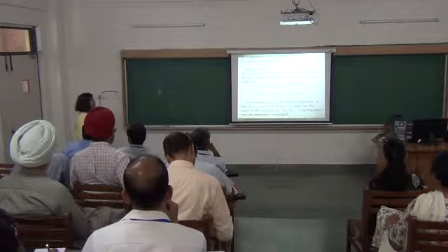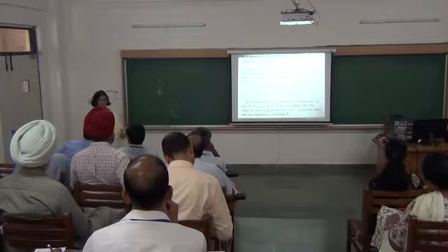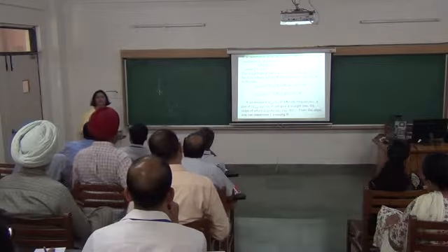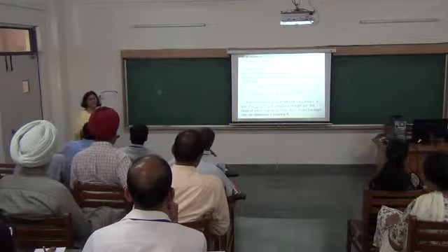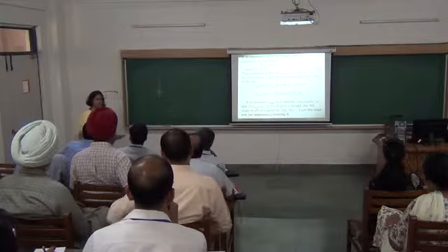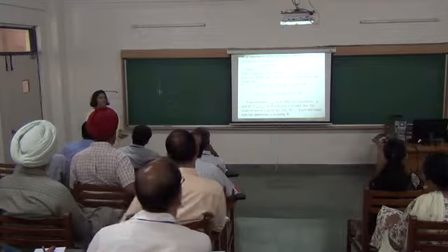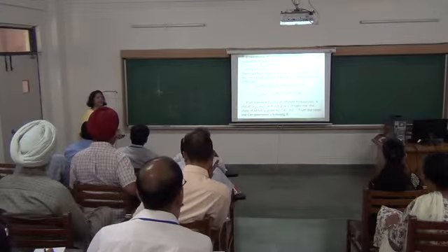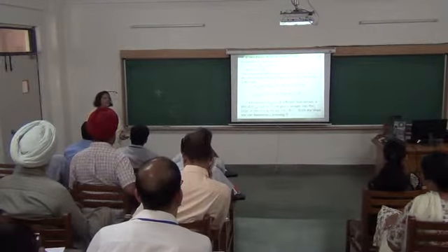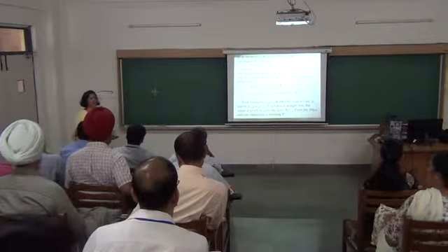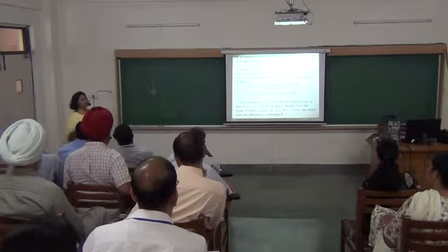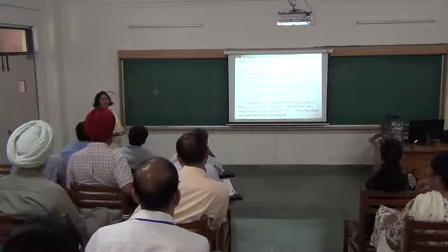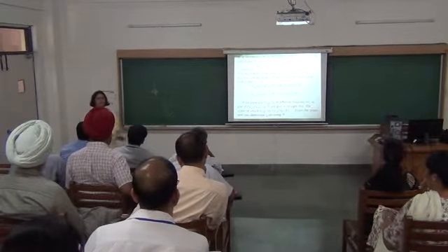This we use because it's much easier if I take my voltage as e raised to j omega t rather than sin and cos, because second order differential equations come in LCR circuits and all that. It's very easy to solve if it is exponential. And at the end, because e raised to j theta we know is cos theta plus j sin theta, depending on what voltage I want, cos or sin, you can choose the real or imaginary part at the end.